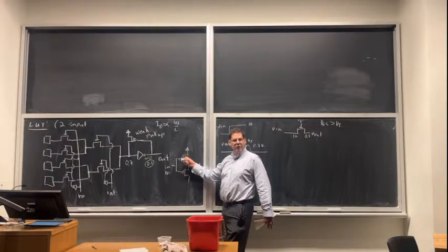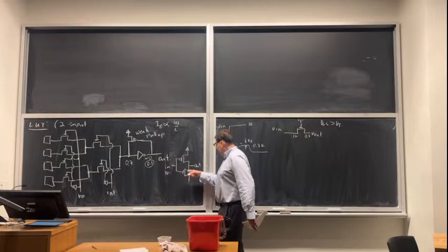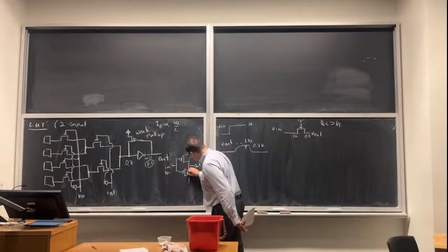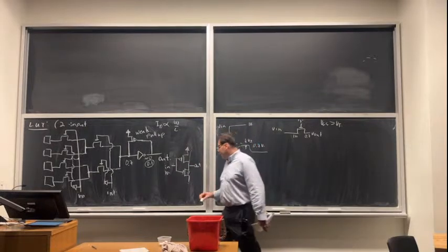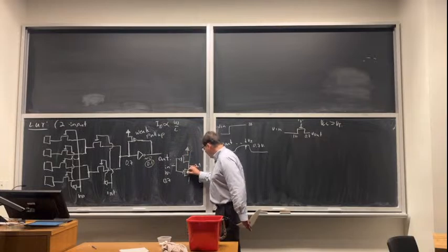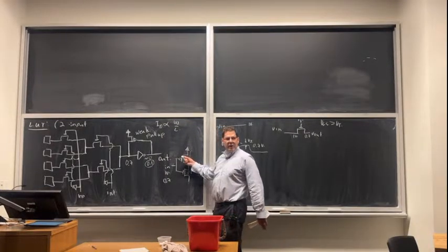No DC path. I put a logic 0, this is completely off, this is strongly on, but there's no path that just sends current down here. If I put 0.7 volts into here, this is pretty on, mostly on. This is just barely off.